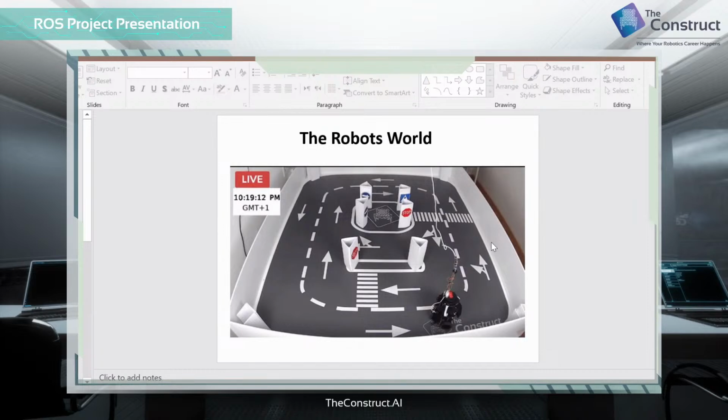If the robot's right side reading is bigger than 0.3 meters, the robot will go a bit to the right, as if it will be crashing into the wall. Then when it is 0.2 or smaller than 0.2, it will come back. In this way, we will have something smooth, and we will be able to make it go in a straight way.